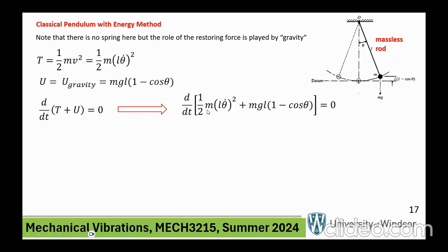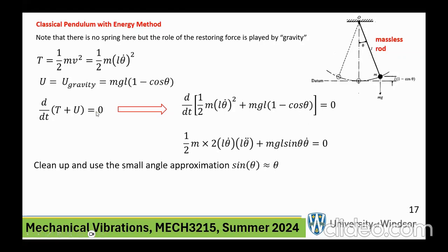There may be some energy friction because of the joints and things like that, but this point is not moving, so that's all right. Just clean it up, differentiate with respect to theta. If you differentiate theta dot squared with respect to theta, you're going to get theta dot, theta double dot. Two of them.